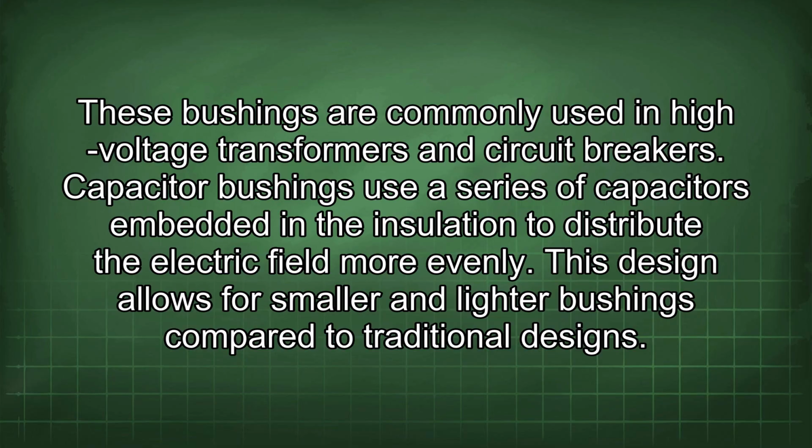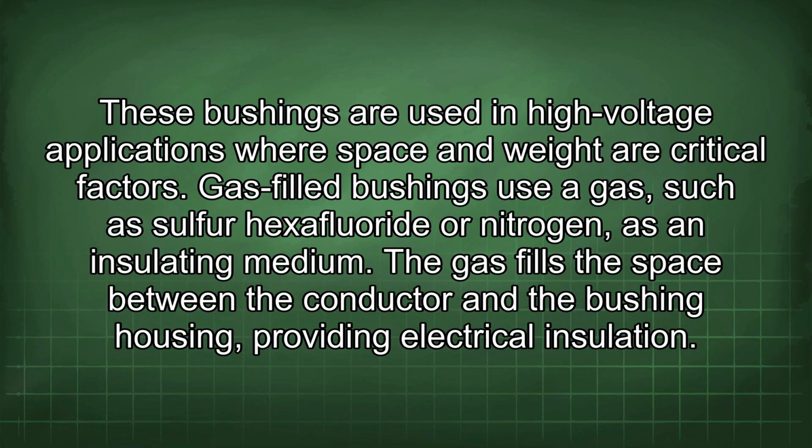Capacitor bushings use a series of capacitors embedded in the insulation to distribute the electric field more evenly. This design allows for smaller and lighter bushings compared to traditional designs. These bushings are used in high-voltage applications where space and weight are critical factors.